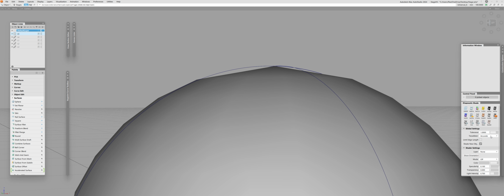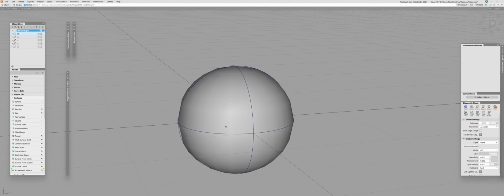So how is it done? In simple terms, there are 4 steps. Now the first one, I'm just going to zoom out. The first one is parametric representation. So Alias builds an underlying math structure of NURBS geometry that is created by your inputs. So I created the sphere here, it took my input, it created an underlying math structure of NURBS geometry. Second is evaluation. Surfaces will be evaluated at numerous points along a parametric domain of NURBS. NURBS, as you probably know, is a two-dimensional domain of points that is defined by polynomials. This means calculating the precise positions of the surface for a grid of parameter values.